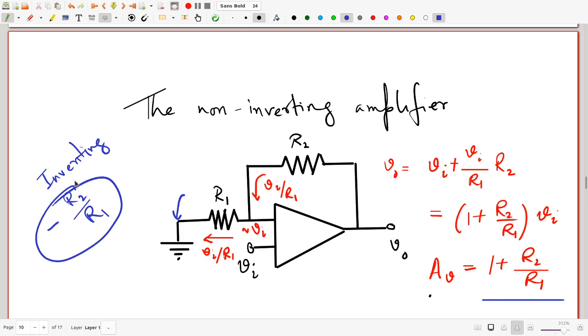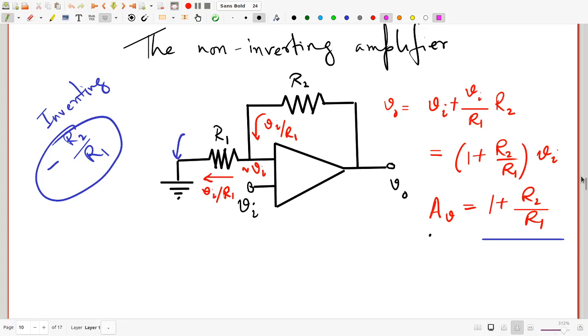The low input impedance of the inverting amplifier circuit essentially means that you are drawing a lot of current from the previous stage, and that may actually cause a large drop before the input is reached, and that may severely impact the performance of this system. Since coupling many amplifier stages together to get to a desired mathematical expression is often done in op-amp circuits, this may become a bit of a problem.